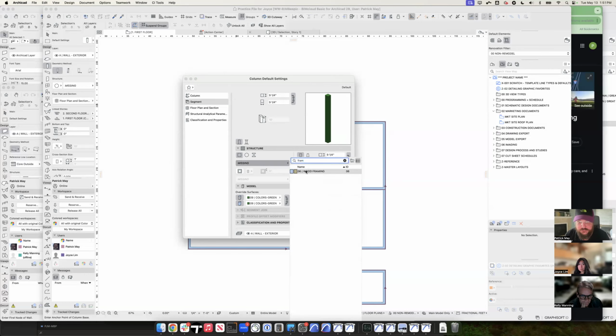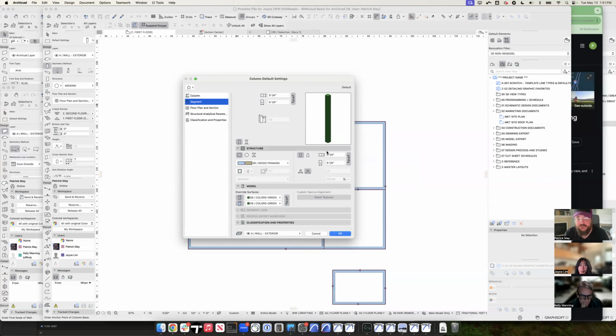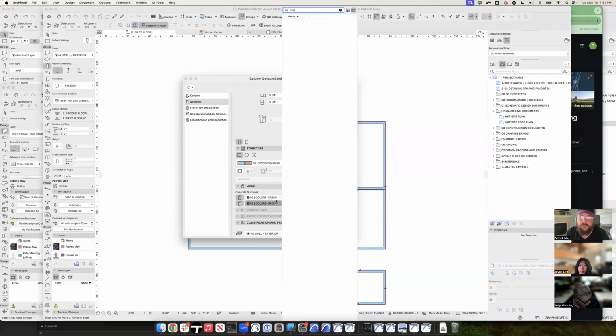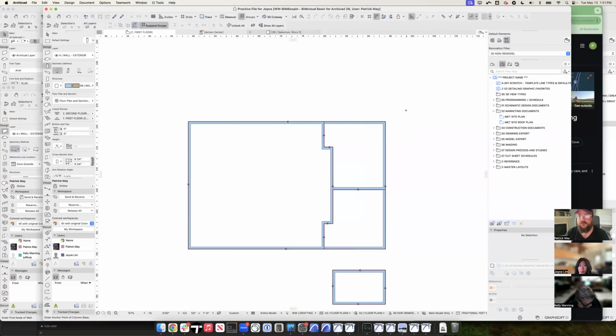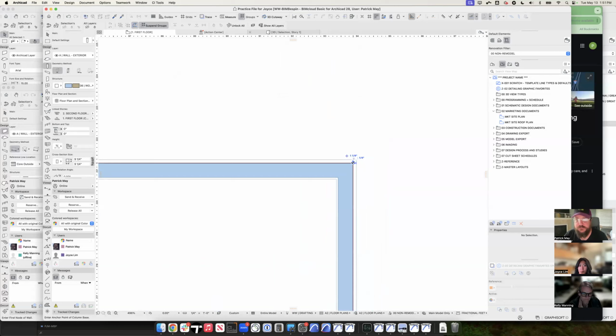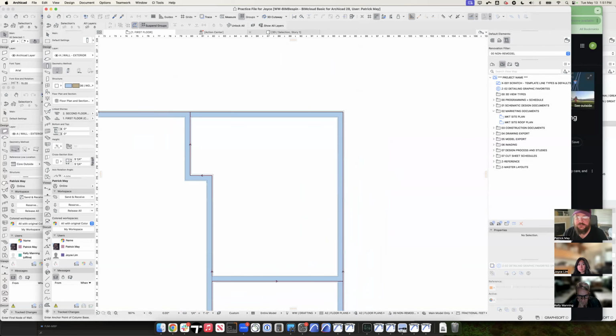I'm going to say that this is wood framing. It's still a 10 by 10. And we'll make it trim. Wood SD, we'll use that one. Now, if I hover over this corner, I should be able to, on my y-axis, say that this is like 12 feet up, and it should dump it right there.